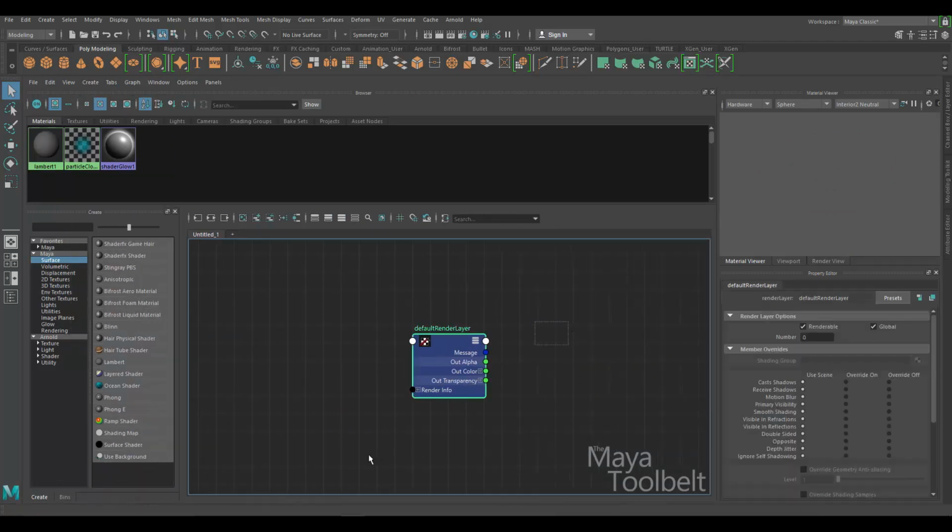If you ever have something in your work area that you don't want, like this for example, select it, and then up here there are these two buttons. One's got a plus sign, one's got a minus sign. Click on the minus button. It will remove it without actually deleting it. So it still exists in my Maya file, but it's no longer showing in my Hypershade work area.